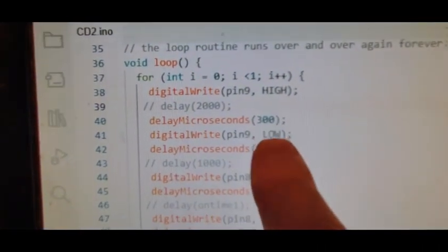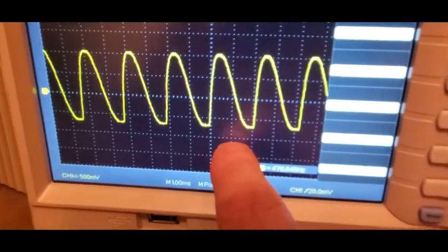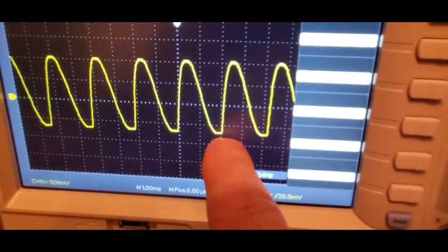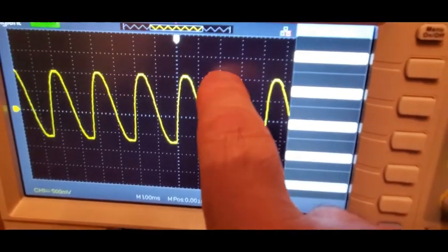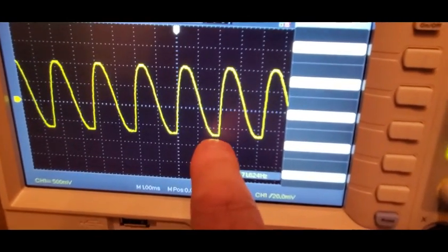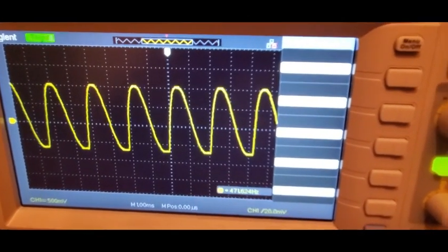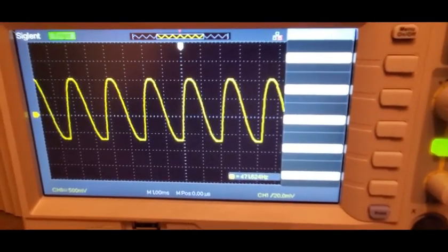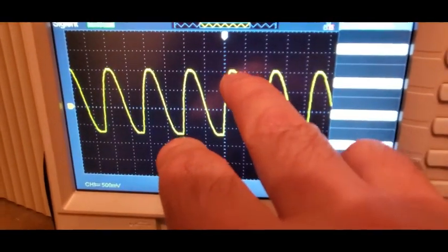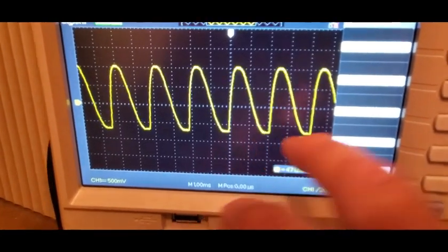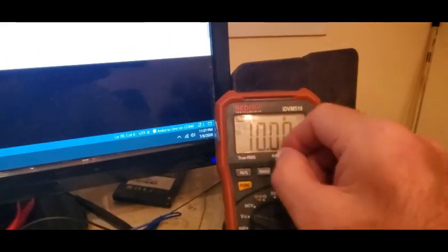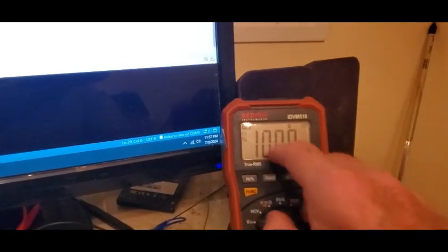There's the waveform from this, where it discharges and then it goes negative, it's sitting there for a while, and then you're just charging it all the way back up. Now we could change that, but that's what it's doing now. What we want to know is how far negative did it go? Before, when we were at 3.6, it looked like it went to negative 2.6.